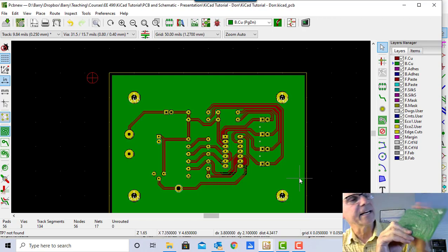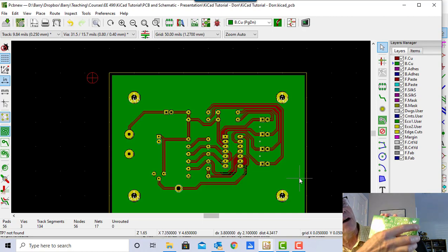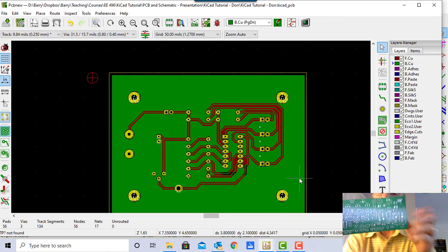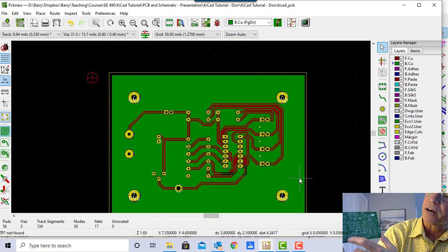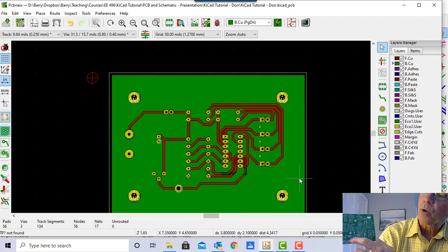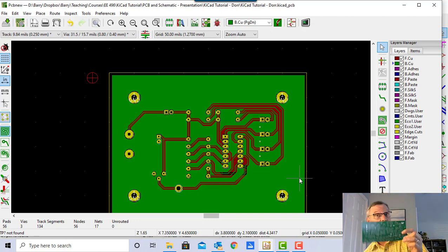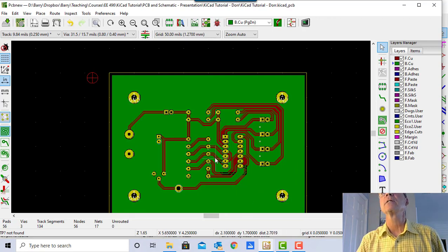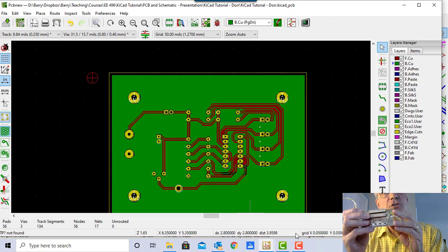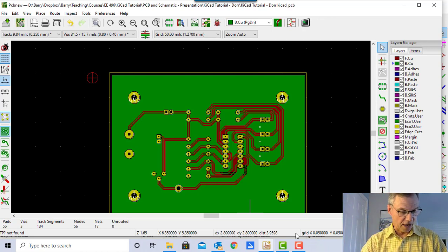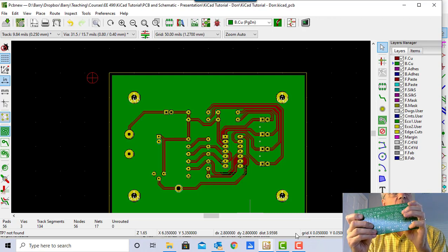Like, you can't really see it here, but the silkscreen kind of outlines all my components, especially these big power transistors here. It actually shows where they go, and it shows which power transistor to put in here, because I've got to make this thing pretty idiot proof, because it's a kit and I assemble a lot of them myself, so I need that. So if you do an SDSU board, you're not going to get a silkscreen. If you do a professional board, you will get a silkscreen.